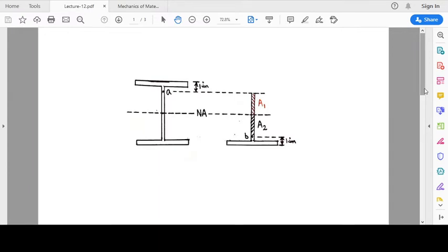As I said, if you were to find the value of Q, if we are to find the value of shear stress at a point A on the cross section, you can either consider the portion of the cross section above this point, or the portion of the cross section below this point. Both are going to give you the same value of Q. Let me elaborate that a little further. We have already done the upper portion in the solution of the problem.